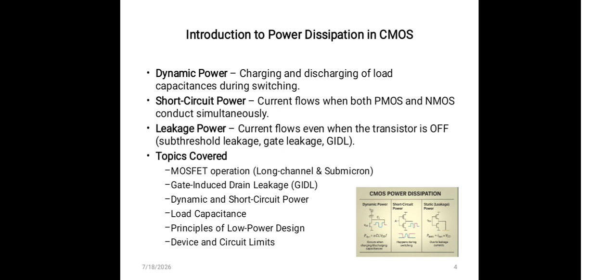And the second case is short circuit power dissipation. Whenever the input changes, there is a very short period of time during which both PMOS and NMOS transistors conduct simultaneously.